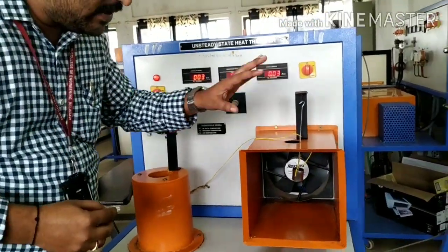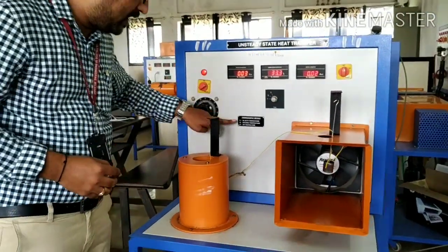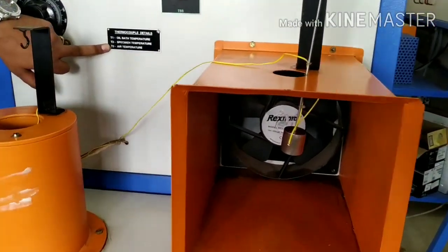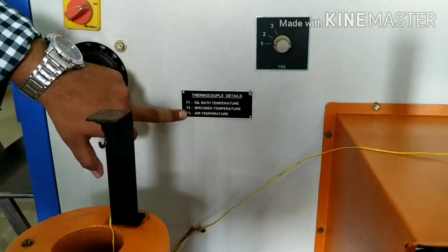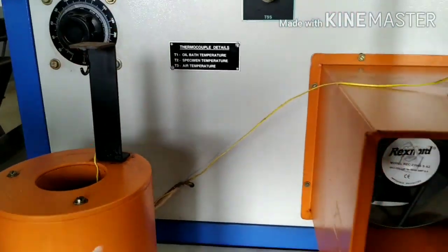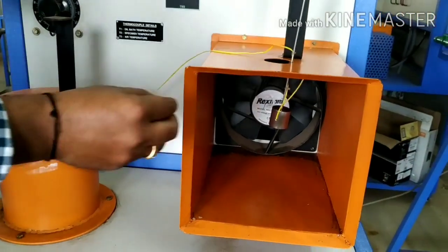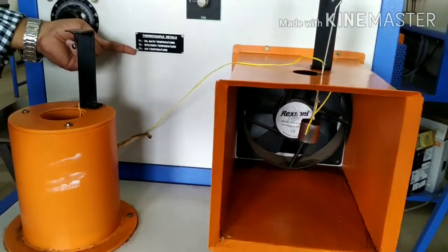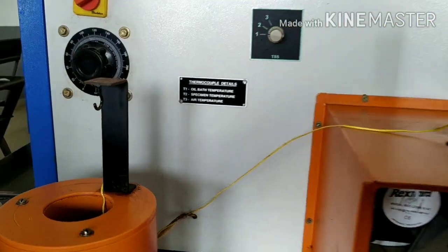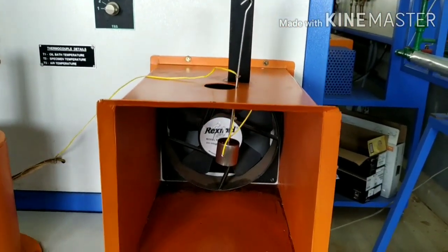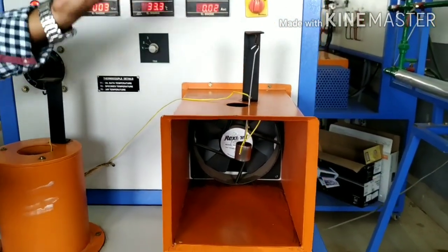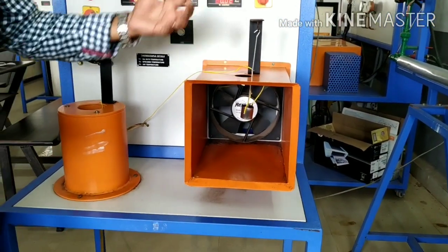Before we do this experimentation, we are going to note down one more temperature, which is the temperature of the air. We call it T3. There is a thermocouple placed in the chamber which will measure the temperature of the air. Before the start of the second part of the experiment, when the time taken is t equal to 0, we first measure the temperature of the air. Then we insert the specimen, which is a hot body, into the flowing air. Convection occurs, and slowly the air starts grabbing the energy from the specimen and it starts cooling down.